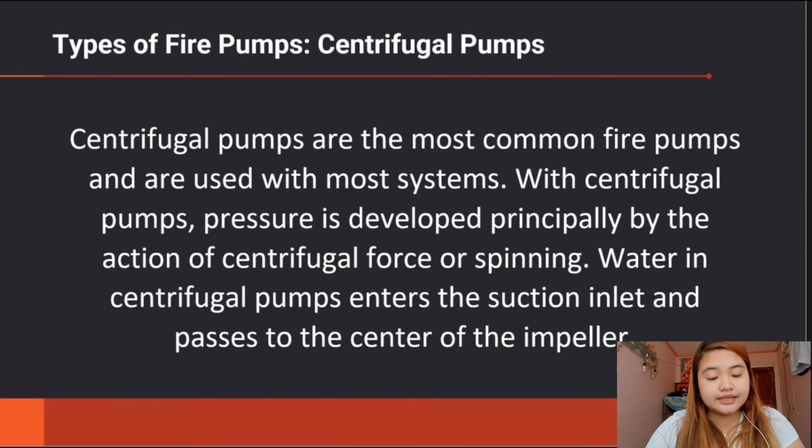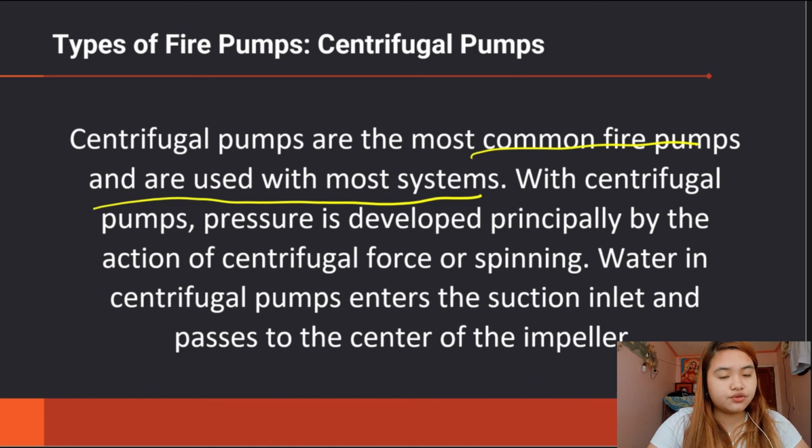So the other one is the centrifugal pumps. These are common fire pumps which are used in most of our systems. With this, the pressure is developed principally by the action of the centrifugal force or the spinning. Water in centrifugal pumps enters the suction inlet and passes through the center of the impeller.